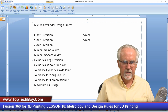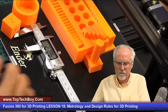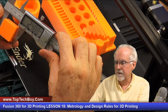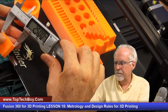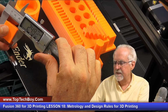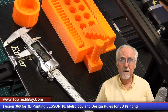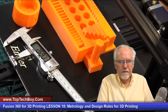Okay, now let's come in for z-axis precision. We did some of this a couple of weeks ago, we just didn't write it down, but now we're more formally writing it down. So we're going to look along the z-axis. And in this case, what you can see is it's coming up a little bit smaller than I expected. I'm just eyeballing it. You could more formally average. But as I go across here, I'm seeing overall that it is about 1/10 of a millimeter less than what I expected. So z-axis precision is 0.1 millimeter.